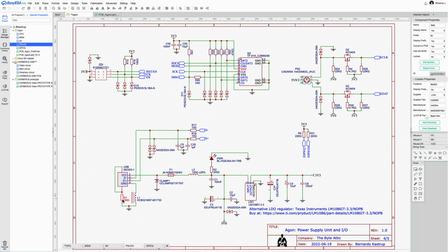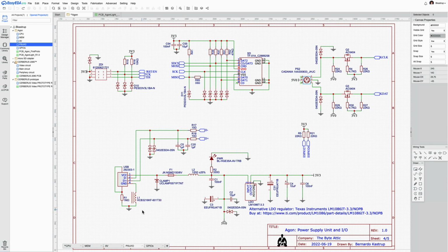Now, is this really necessary? Most likely not. But again, it's the kind of thing that costs nothing, doesn't make the layout much more complicated, so why not? Now, this is just a clamp. It works as a safety if there is overvoltage, then this diode here will open, even though it's biased the other way around. It will open and the excess energy will flow to ground.